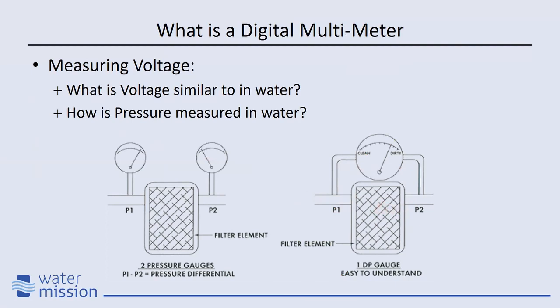Now, another thing to think about is how much water is flowing through this pressure gauge. None, right? We really don't want any water flowing through this pressure gauge, because if we were to install a parallel pipe like this, but we allowed water to flow through it, if you had 20% of your water flowing through that pipe, the pressure is going to be different. You can't even read that anymore. So the pressure gauge has very high resistance to flow, okay? And that's going to be important to think about a little bit later on.